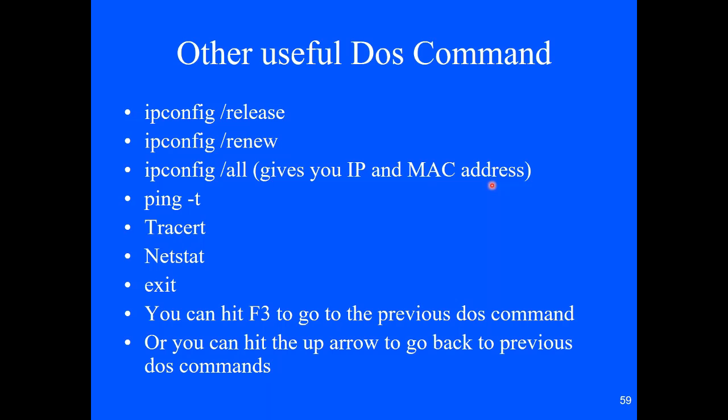A MAC address is a way to identify the computer, and every manufacturer, when they have IP addresses, automatically has a MAC address. And typically the first 2 octets of that is assigned to a manufacturer. So like Multilin's got it where you can have Discover, and because they know their MAC address of all their devices starts off a certain way, they can find all the MAC addresses and automatically tell you what the IP addresses are because of that. And that's kind of what Siemens and some of the other manufacturers do.